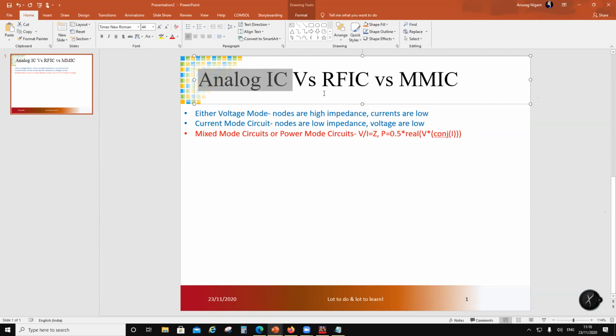So when the gain is for a very small input voltage range, let's say the bias point drifts. For example, a common source amplifier, or a common gate amplifier, is a single-ended amplifier. But if it has a high gain, then the input voltage range is very small. So the bias point should be at the center of that input voltage range to have sufficient gain. Here the voltage can drift with temperature, with process, with aging. So it is not advisable to build a high gain stage with single-ended circuits. Then you put differential circuits.